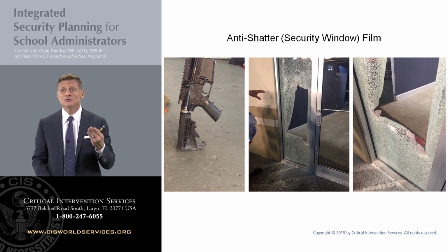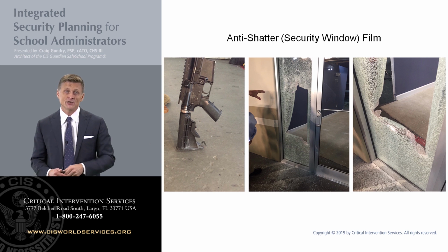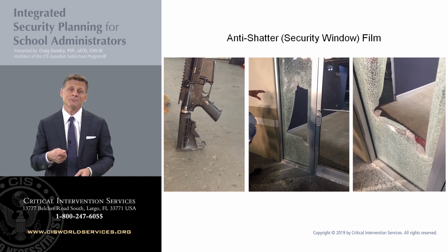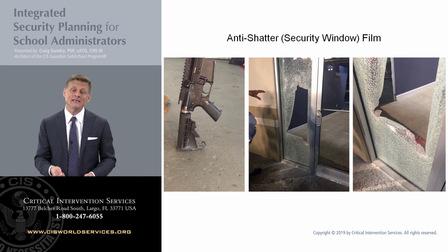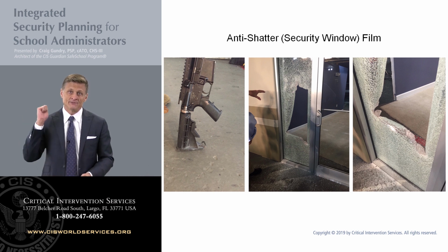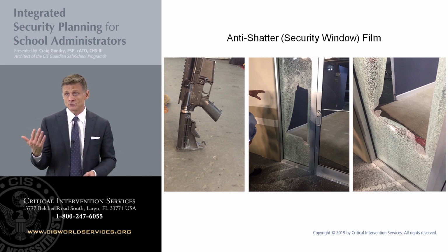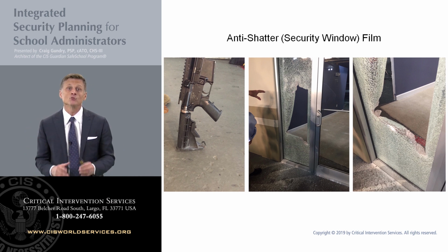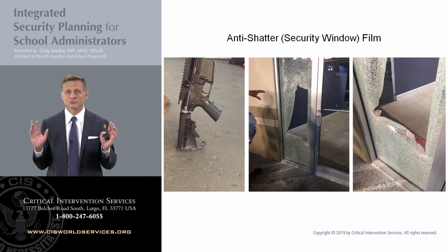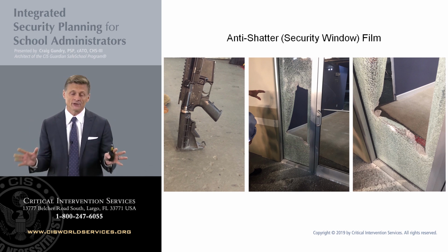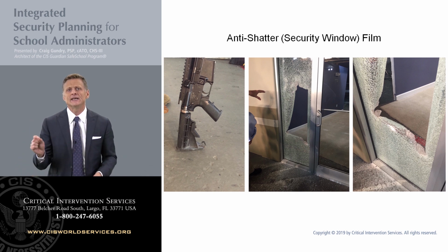Now keep in mind that 45-second delay time that I mentioned a moment ago is the best time. That was the one scenario where my penetration tester actually turned the weapon almost into a hatchet and was beating through the window with extreme aggression. And in fact, he hit that window so hard that he actually bent the buffer tube of the rifle, which would have rendered that rifle inoperative. So if you were to be expecting a reasonable performance out of film reinforced windows, you could be looking at something around the 60-second time period.